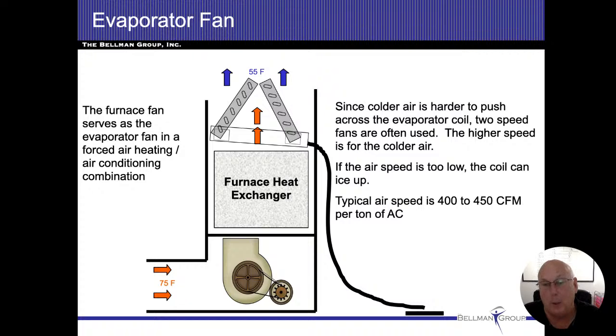In which case, I think you're always better off putting a furnace in. That's just my 2 cents. Just because if something goes down with the steam heat or the hydronic heat, at least you've got another backup system that comes in there. Not only that, but you can circulate air and filter that air as well. You can't always do that with steam and with hydronic. You can also add a humidifier on these things. There's a lot of other bonuses that you could add to go ahead and make your home more comfortable.